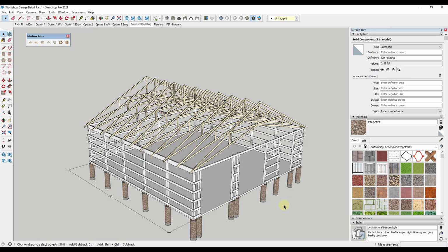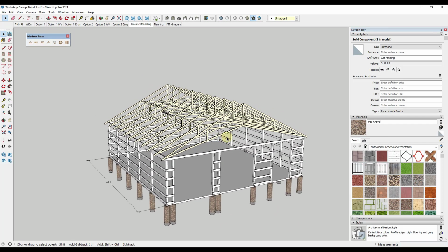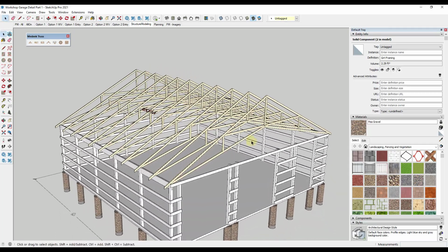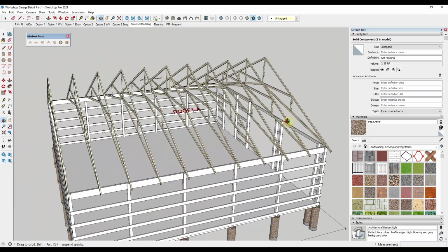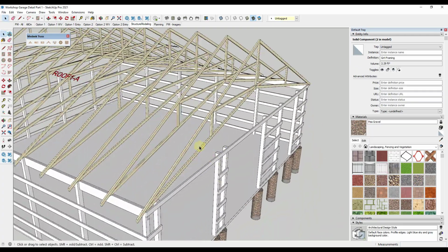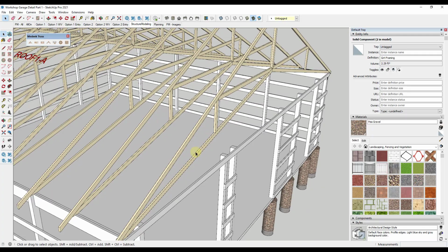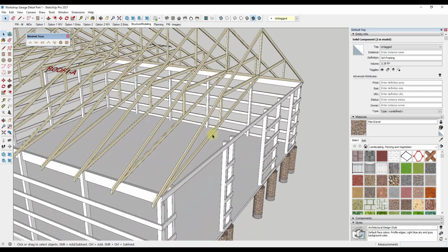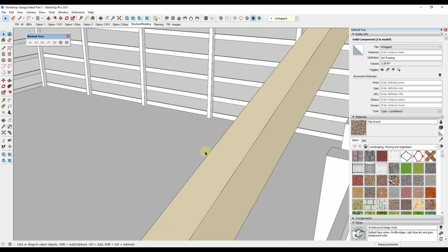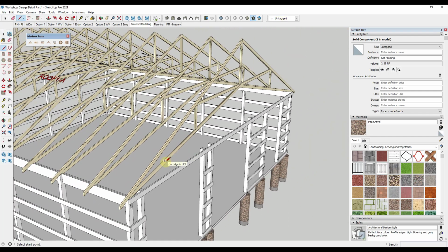So now I've got my trusses in here. One thing that I didn't know when I did this the last time is you actually need bottom chord bracing running along these trusses. So basically what that means is that you have to brace these on the bottom to keep them from twisting. So it's something that I actually had to rent a lift and do the last time I did a building like this, which was kind of fun, but definitely an expense that I didn't want.